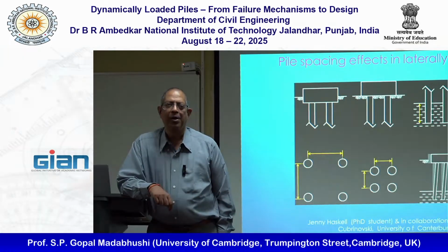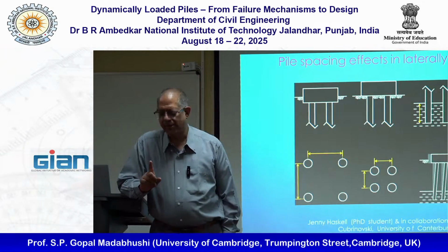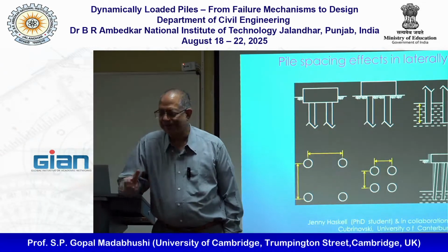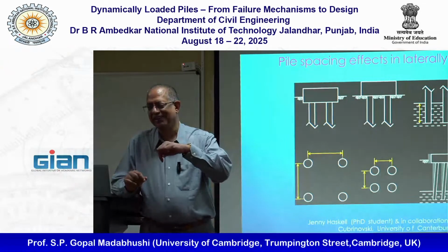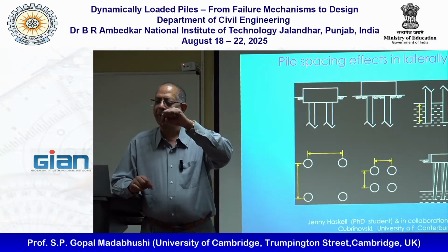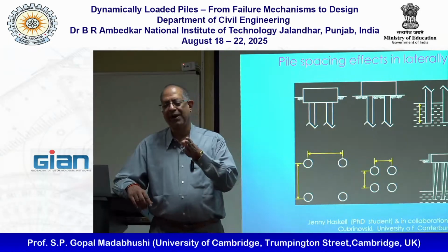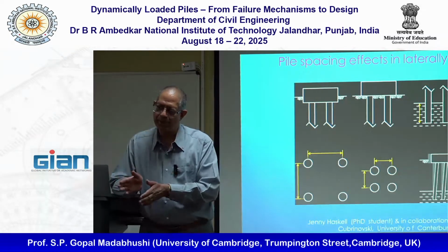Yeah. But there are other things that go around, like, for example, Dave White, we were talking about him earlier. One of the things his PhD was on was driving a pile, leaving it for some time, and trying to do a pile load test on it. And what he observed was that the pile load capacity goes up if you leave it for a certain amount of time.